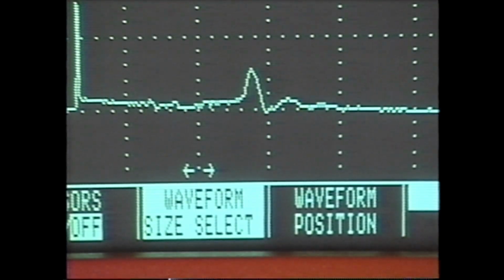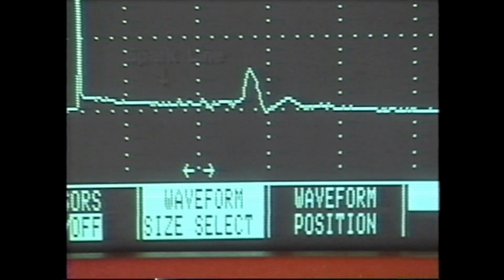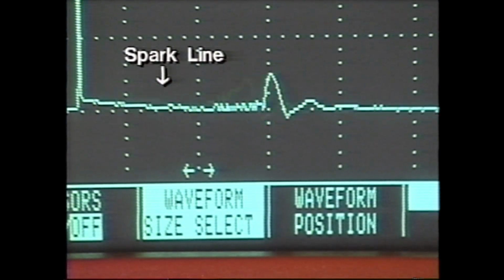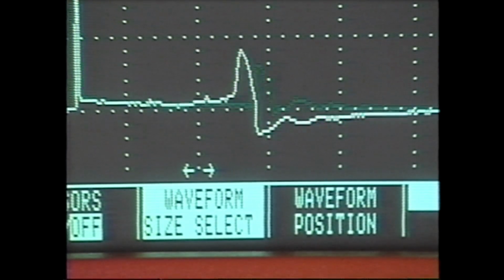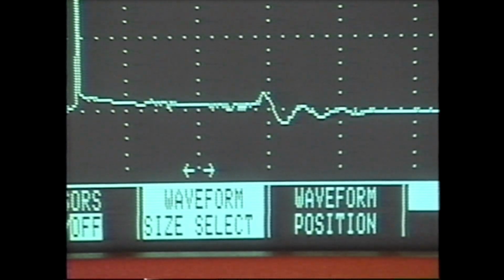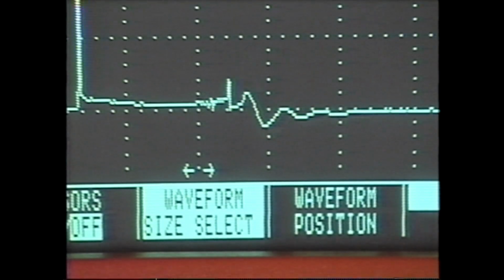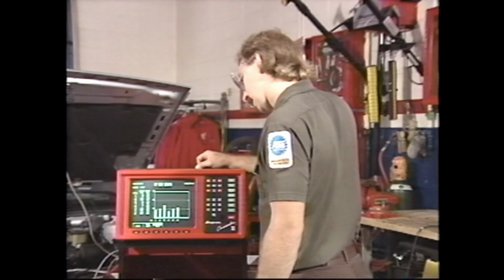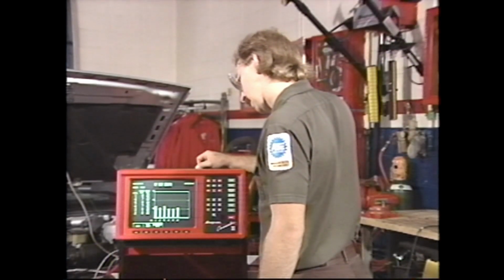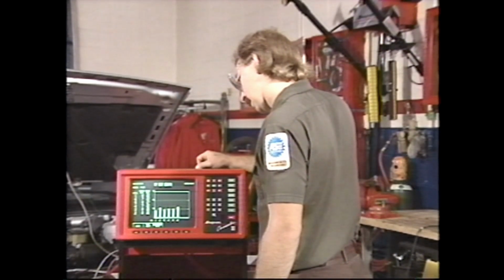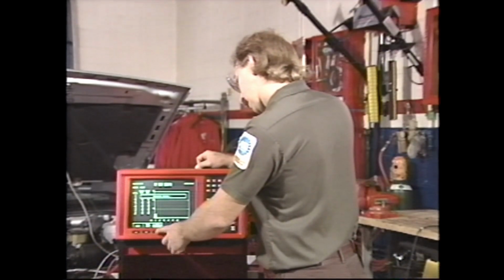Increased resistance appears as a slight rise at the end of the spark line. After the spark extinguishes, remaining energy dissipates. This is seen in the waveform as diminishing oscillations. Use the secondary menu test screens to check distributorless ignition activity, firing voltage requirements, and spark burn time.